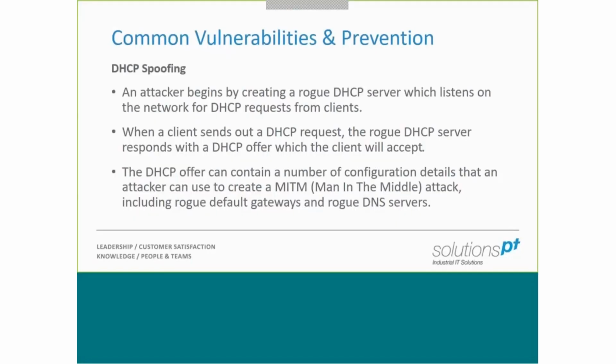Okay. Moving on to DHCP, again, another protocol that's not inherently secure, a little bit like ARP, never designed with cyber in mind. Yes, exactly. I think more designed for just ease of use. So a DHCP server will give out your IP addresses and network information to your clients, whether those clients be PLC, HMI, a workstation, anything that supports IP will most likely support DHCP.